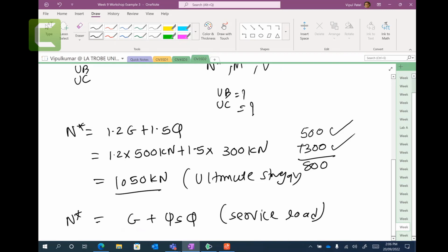In the USA, a bridge collapsed because of the asphalt, that black stuff that you put on the road. They did the repair so many times. Every time they went on the bridge and saw some damage on the road, they put a new layer. After a couple of years, they found damage and put a new layer again. They kept putting new layers, and the bridge collapsed. Why did the bridge collapse? Because of the dead load. You keep increasing the dead load, and that bridge was not designed for that kind of dead load. So therefore, this is just extra. Okay, anyway, that's not our business.